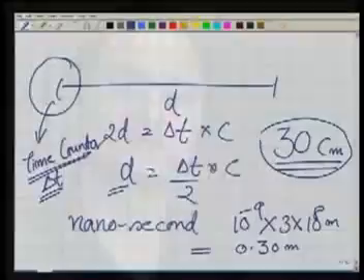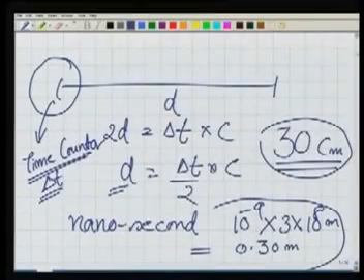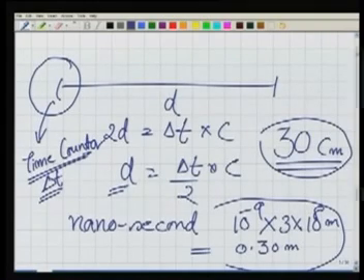Even if our time counter is very precise, and its least count is in nanoseconds, we are committing an error of the order of 30 centimeter in our measurements. You can do this computation, you can find the values. Now, 30 centimeter error in distance measurement is too large, because we are making use of EDMI in order to measure at the millimeter level.